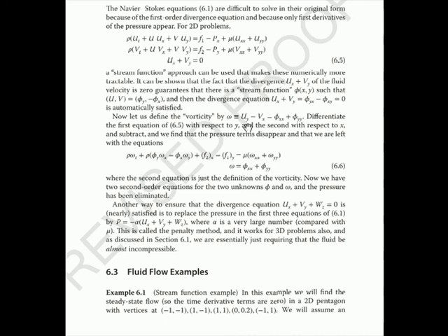And the vorticity is also going to be 0 on the bottom. Why? Because, remember, u sub y equals 0 is the other boundary condition, and v sub x, v is 0 along the entire bottom boundary, so the horizontal derivative is 0. So both of these are 0, therefore omega, the vorticity, is 0. So on the bottom, where we have free flow,